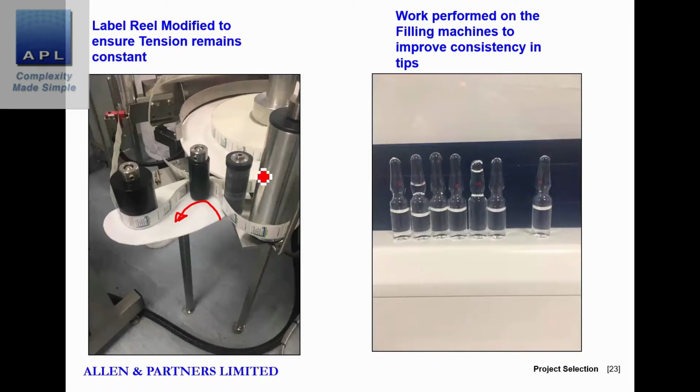And here's the problem with the ampule height. Look, all of these ampules are different heights. This was never a problem before, but now you're trying to get consistency in the labeling machine. Actually, this part of the process, the sealing part, is really important. So suddenly they're having to put a standard further up the process that's never been needed before. So we need to improve the consistency there, so all the sensors work and things like that.